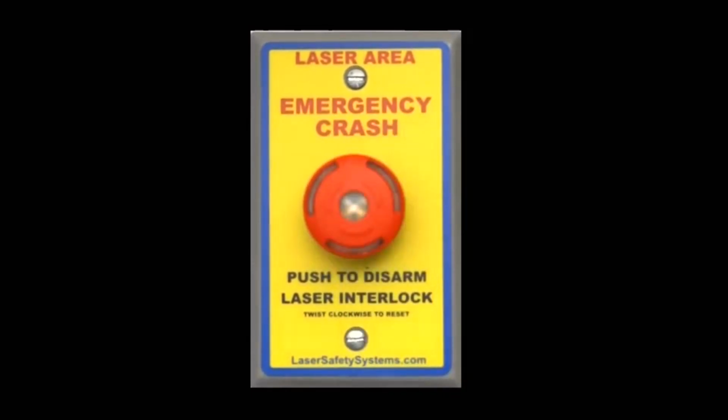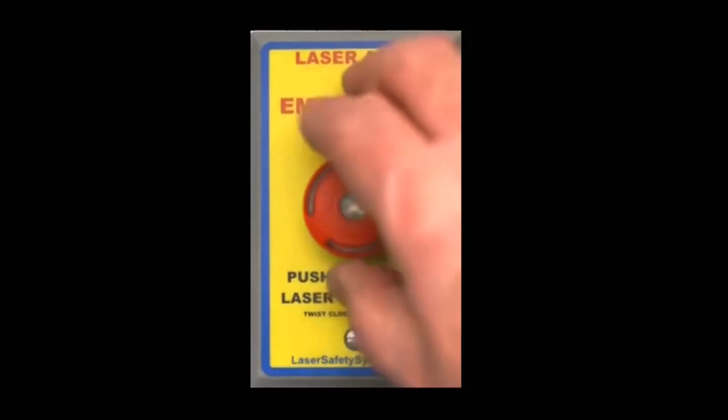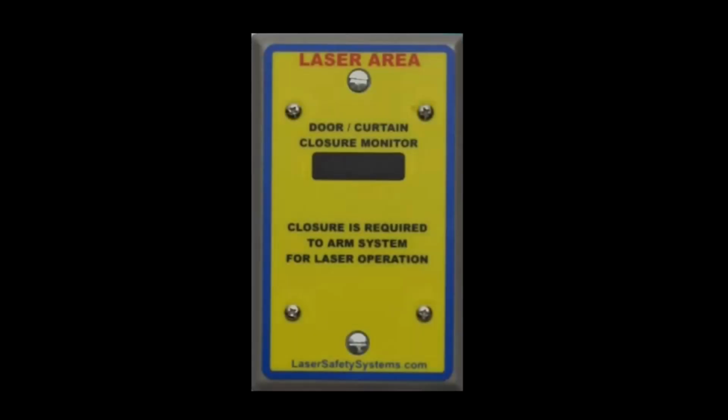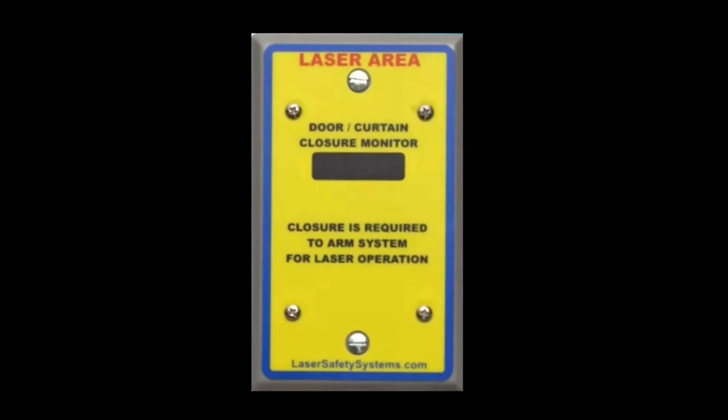If you have one or more of our LSS-2383 emergency crash modules installed, one of them may have been depressed and you'll need to twist them slightly clockwise to ensure they are released. If you have our LSS-2387 non-defeatable door or curtain monitor, you want to look at the display for the illuminated closed text. If it is not illuminated, you'll need to close the door or curtain to satisfy the interlock.